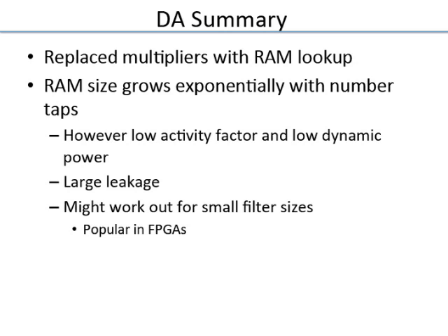But it has a very low activity factor, because whenever you have a memory, none of the bits, nothing except for one row, everyone else is just quiet. So the activity factor is very good for memory. But it can have a lot of leakage, and so there are pluses and minuses and so on. So this kind of thing is used. People find it very suitable for FPGAs, which have a lot of memories anyway lying around.